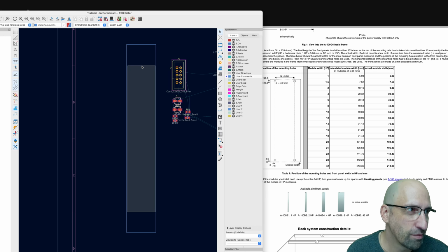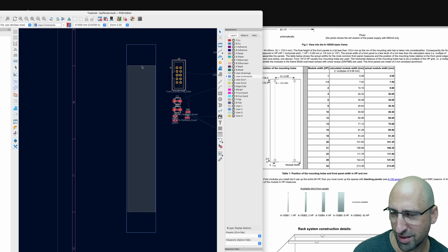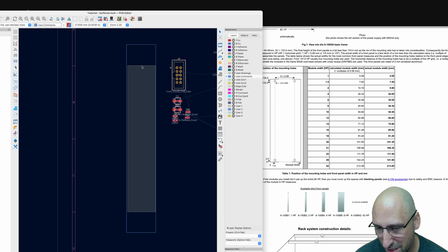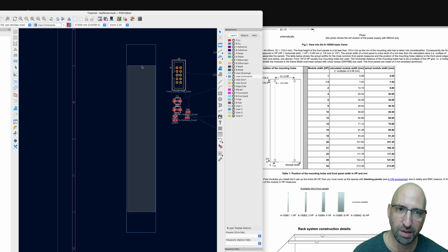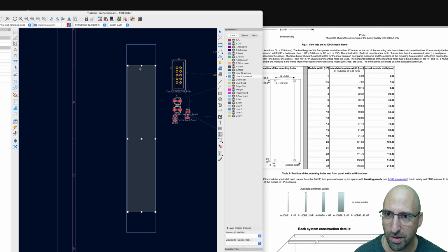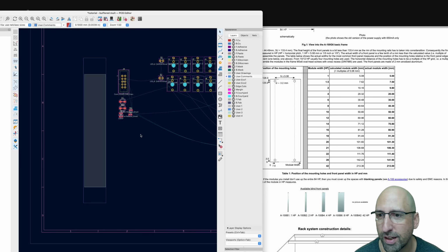I think I've made boards successfully up to about 110 millimeters, and that's really cutting it fine, depending on the kinds of rails you've got and so on. So even if we could make this a little taller to squeeze more components onto it, it's not really going to help us that much, and it's going to cost a whole lot more. So yeah, those are the reasons.